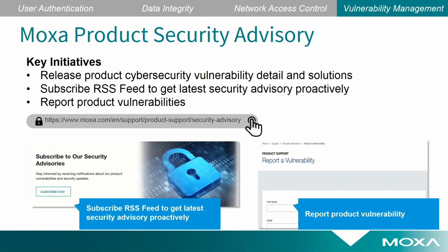And I think one more thing that we're particularly seeing more and more of is, on the IT side, it's pretty common for suppliers to have robust systems and processes around vulnerability management. On the OT side, we don't see that is true across all suppliers. So make sure you're working with somebody that's got a legitimate process around monitoring to see vulnerabilities in their products, responding to researchers as they find vulnerabilities, and publishing either instructions on how to mitigate those vulnerabilities or firmware patches to mitigate those vulnerabilities.